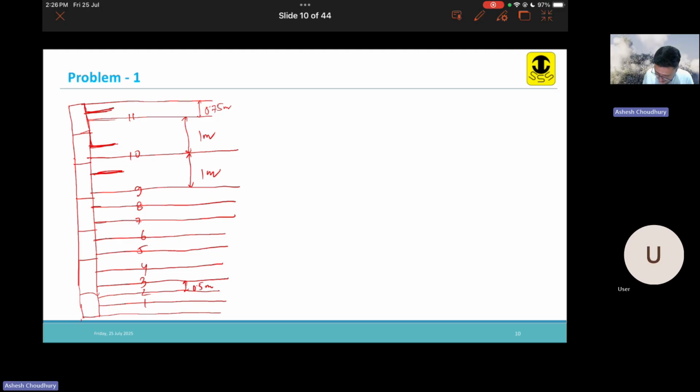Now the next thing is the length. So what is the length of the reinforcement or the geogrid? L_R plus L_E. L_R comes from the geometry of the active wedge, and L_E comes from the embedment depth. Okay, so just find it out.